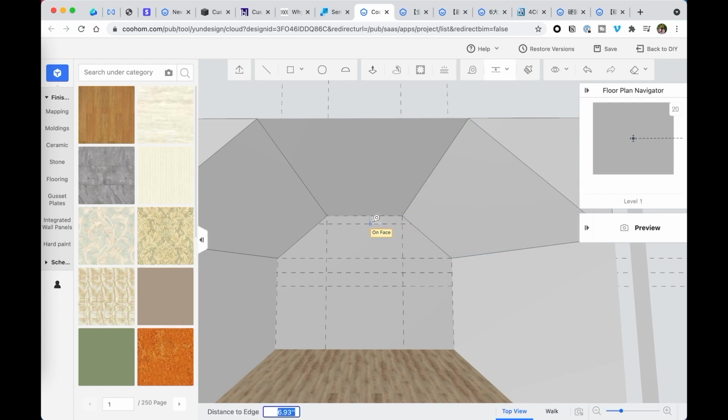So let's make a guideline out of this one. Let's say we want to add a series of wood rafters or beams here. Right? Let's say we want a 6 inch. Okay. Let's offset this to be 6 inches. And see, you can offset directly on the angle surface. Do that for 6 inch. Okay. And then let's delete some extra reference line here.